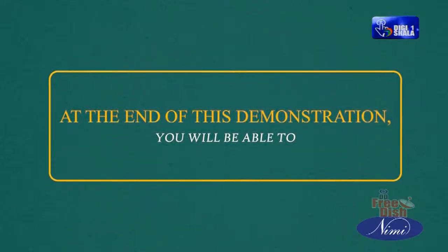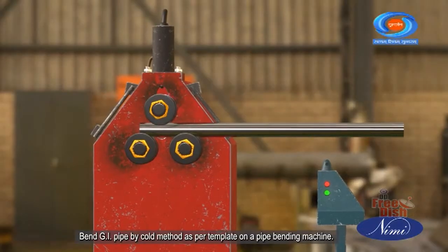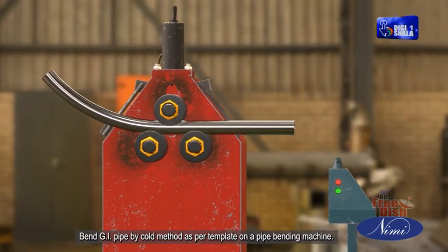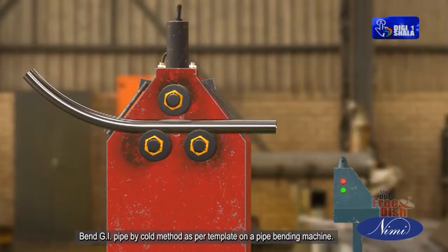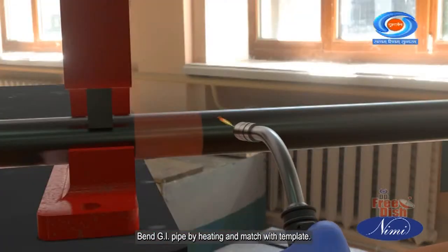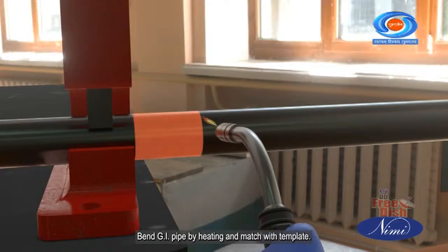At the end of this demonstration, you will be able to bend GI pipe by the cold method as per template on a pipe bending machine. Bend GI pipe by heating and match with template.